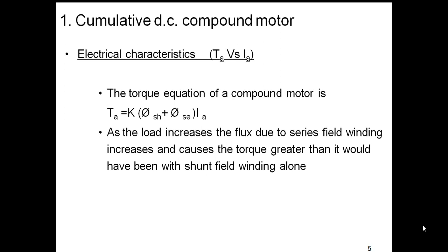And when the load increases, the flux due to series field winding, that is phi SC, increases, and this causes the torque greater than it would have been with shunt field winding alone.